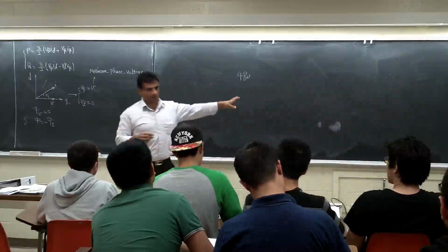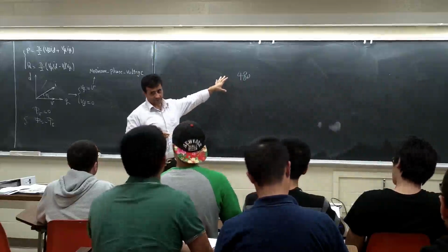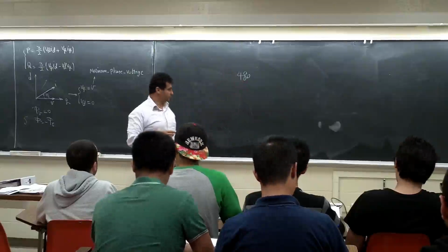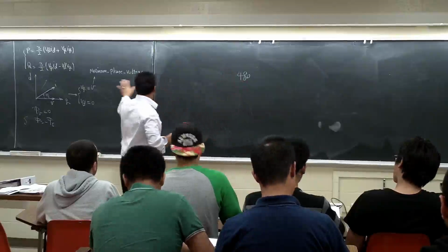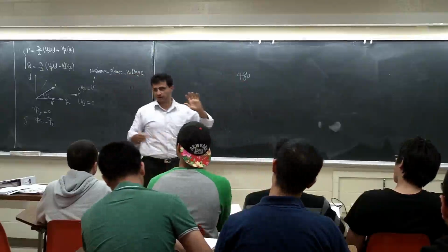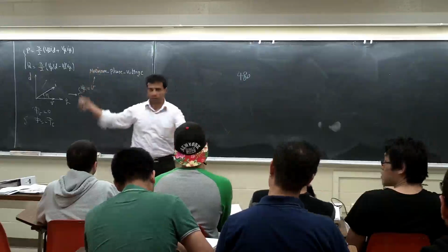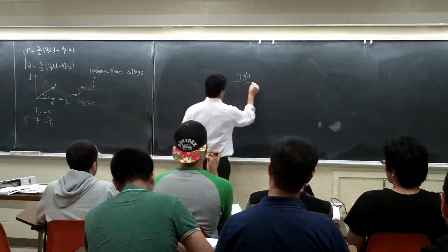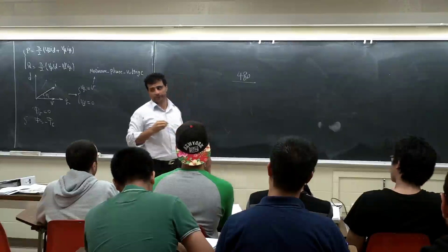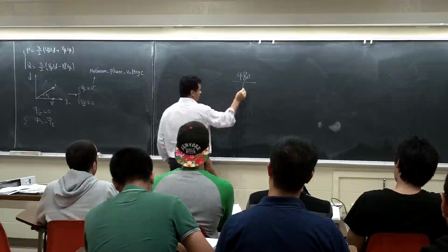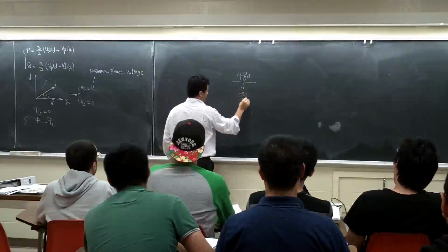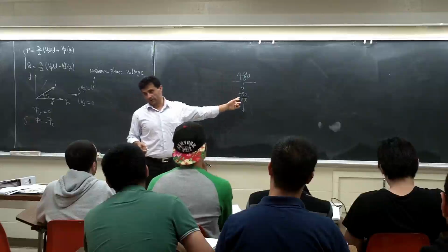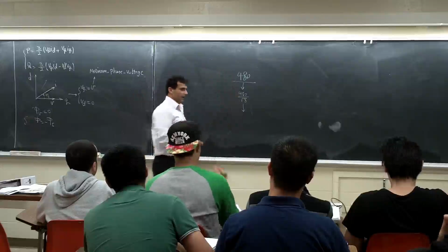But from energy conversion, we said if you have a three-phase system, a given voltage means line to line RMS, right? So when I say maximum phase voltage, this is a three-phase system, and all the equations we went through were for a three-phase inverter connected to the three-phase grid. Now, how much is the RMS voltage of the phase? It's going to be 480 over the square root of 3, right? That is the line voltage; the phase voltage is divided by square root of 3. And so this is the RMS.